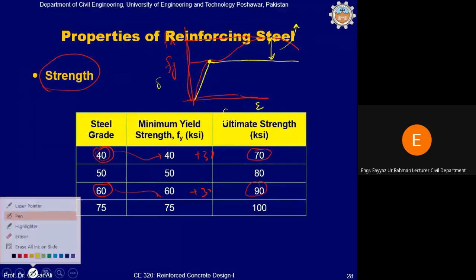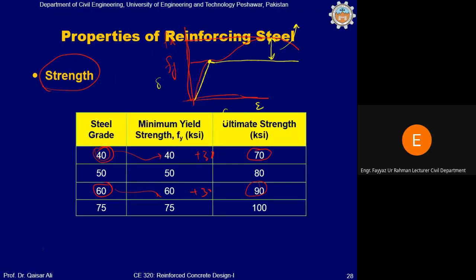What we are doing basically, you will see this in the coming lectures, is that in reinforced concrete mechanics, first of all, from strain compatibility equations, we calculate strains in concrete and reinforcement. And then from those strains, the corresponding stresses are calculated.